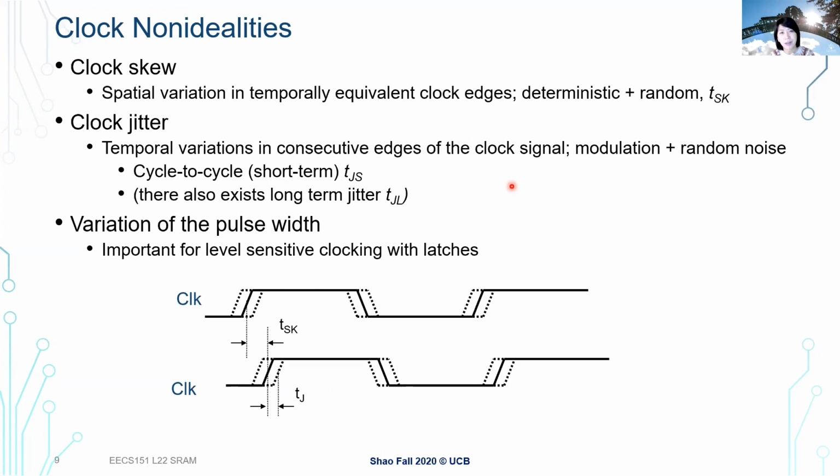So we talked about what those contributing factors are, but eventually all of them affect the way we see the clock, especially across different flip-flops and different registers, with two key factors. We'll briefly talk about the pulses, but typically it's mostly the two key factors. Those are related to what we discussed earlier, how the arrival time of our clock can be different in space and time. So one is the space differences, and another is the time differences. What do I mean by that?